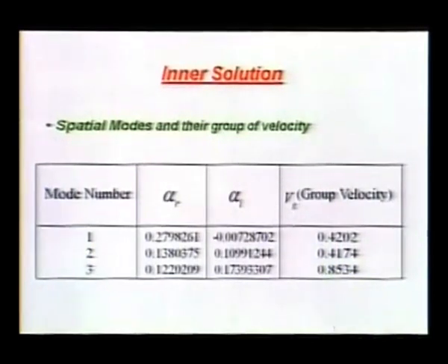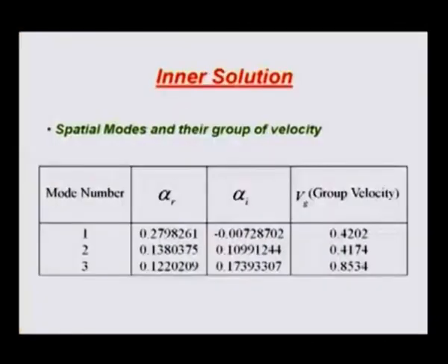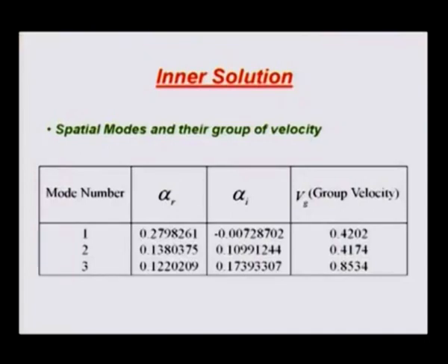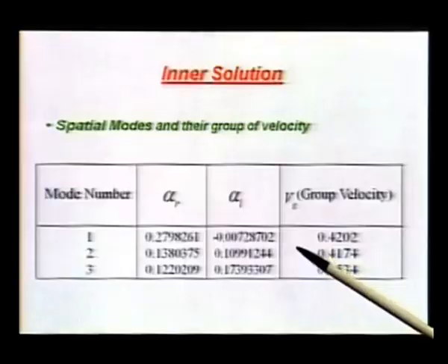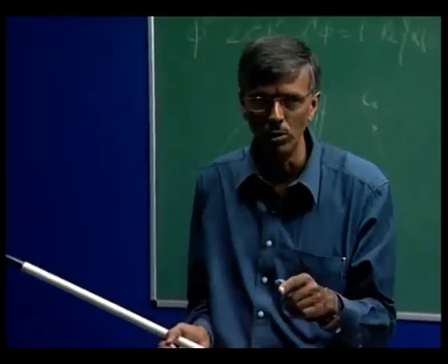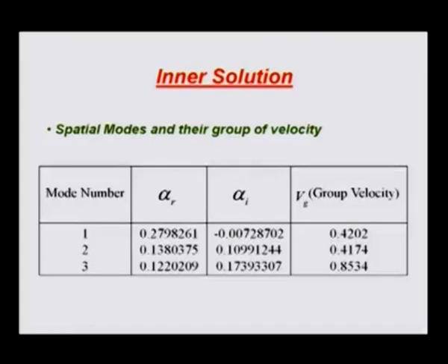This is what Tollmien and Schlichting first found out, and your eigenvalue analysis tries to obtain this. Eigenvalue analysis can also hope to find others, but to my utter amazement, more than 2 decades ago, I found these are not very well done, and we developed the compound matrix method, and we used the grid search method, and we figured out in a box in the alpha plane, say of size 2 by 2 on all sides, only these 3 eigenvalues.